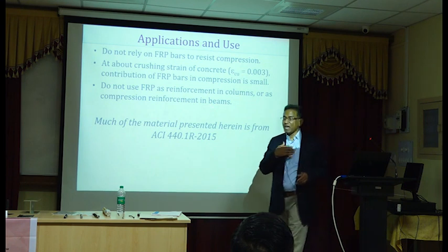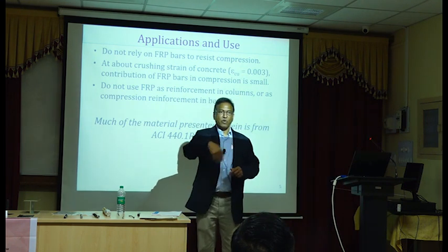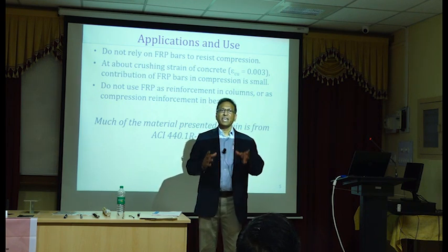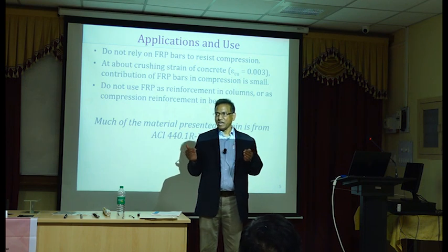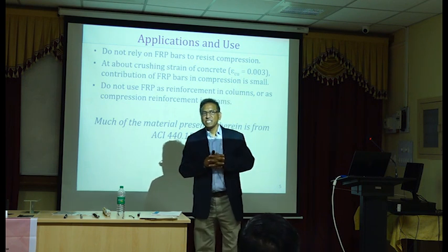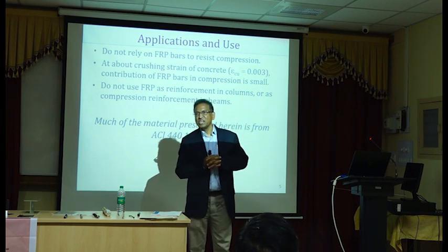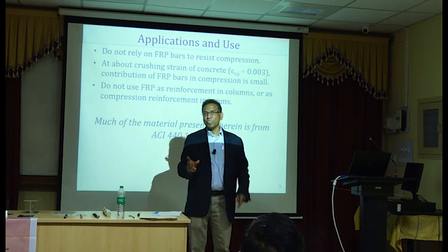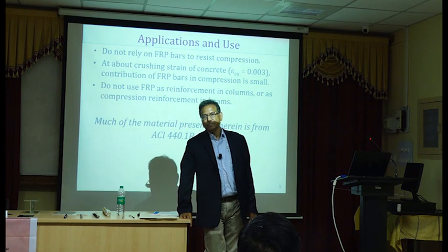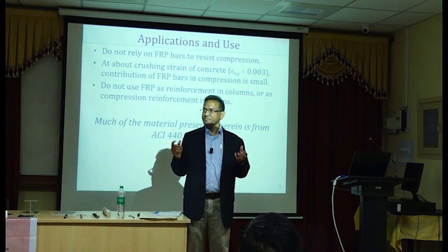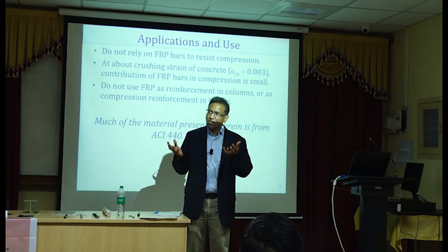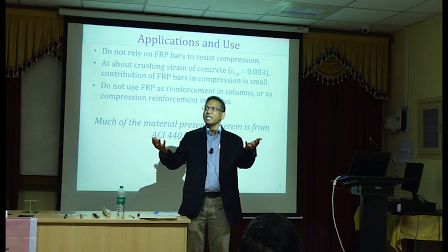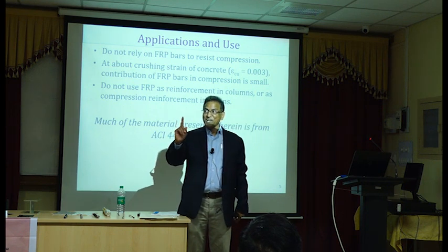And I didn't know this, so I asked one of our colleagues here, are we still using cubes or cylinders? And I hear you are using only cubes still, right? So cube strength is equal to how much of cylinder strength? 80%, right? Roughly 80%. So for the same concrete, you make cubes, you make cylinders. Cylinders will show smaller strength. Very important to know that.